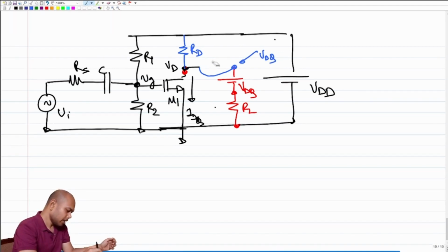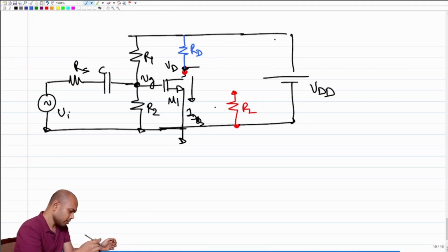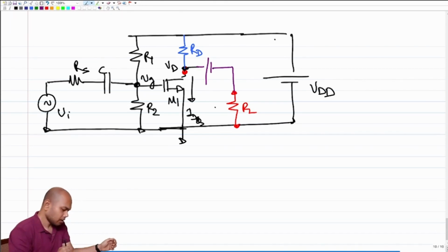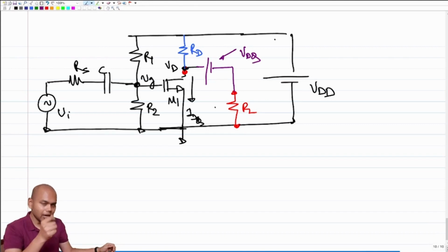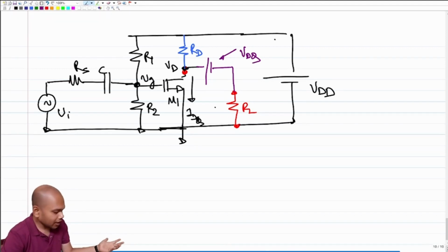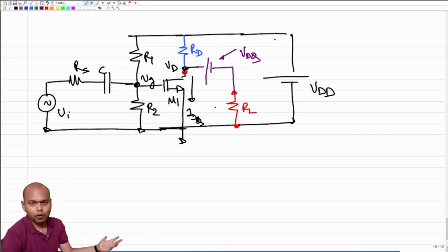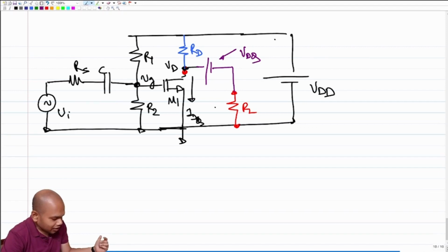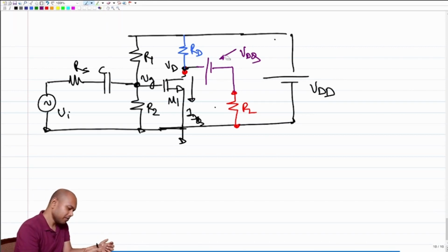Okay, great. So let me make it a slightly better drawing. What is the solution that we come up with? The solution is to identify whatever voltage VD was, VDQ, and include a battery of exactly that value VDQ. Now some of you might get angry with me and say that for half the lecture I have told you that I cannot use a floating battery, so how come I am suddenly using a floating battery? You are absolutely right, we cannot use a floating battery, but now we have a replacement. What is the replacement? An infinite capacitor, right? So instead of using VDQ, what will we use? We'll use a capacitor, right?